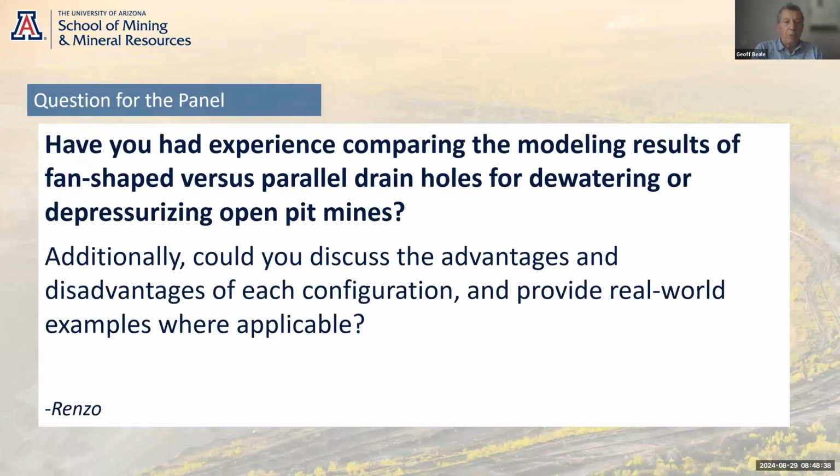So before you actually start the drain holes, you put in the first hole, or maybe the first dry hole, and you make it into a multi-level piezometer, so then you can actually see what the rest of the drains are achieving in terms of pressure reduction.